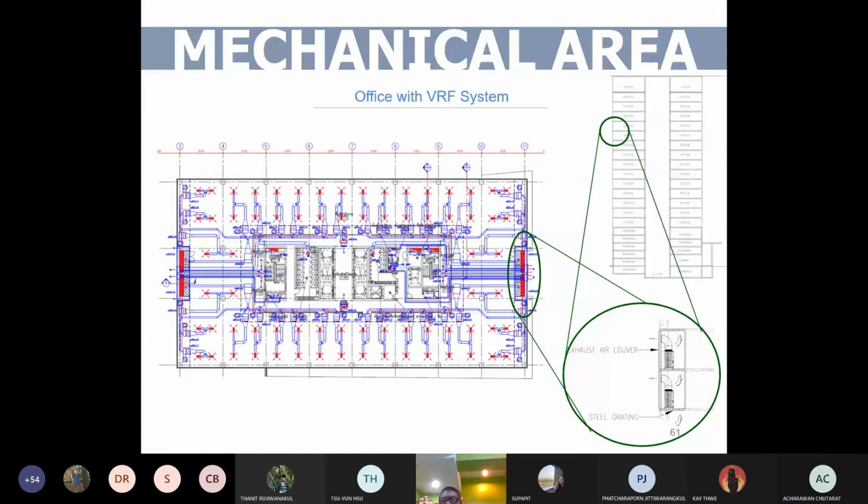For VRF, for student projects, try not to go more than 8 meters. The best is 4 meters. When students prepare the place for putting the condensing unit, it has to be shaded, with careful ventilation and maintenance access. When they have to clean it, they can't do acrobatics climbing the neighboring building.